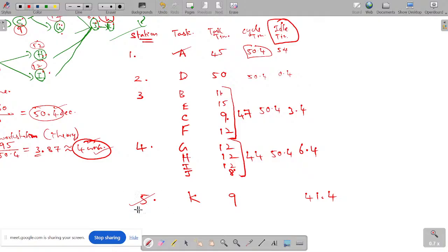So I have a lot of idle time because of this. Probably if you want to avoid this, ultimately we have to focus on this fourth workstation. Can I do something by adding a little more in the fourth workstation? Because already I have 6.4 seconds idle time. There is a remaining 2.6 only, we can check whether something can be done. This is all, probably your job may be over. As I was discussing earlier, I once went for a program and I met Toyota's CEO. So he was saying this: can you give some leftover here and there? Don't we need budgeting here?